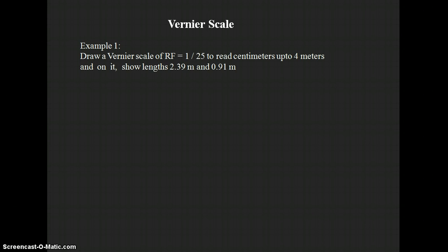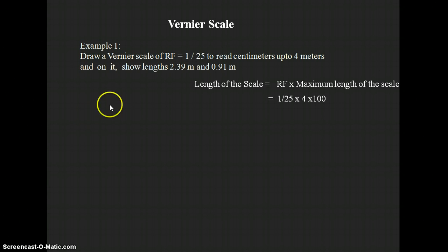So first we find out the maximum length of the scale. That value should be convenient to draw on a drawing sheet. So here the length of the scale can be determined by using the representative factor. The value is representative factor into maximum length of the scale, that is equal to 1 by 25 into 4 into 100. Here the maximum length of the scale in the problem is given as